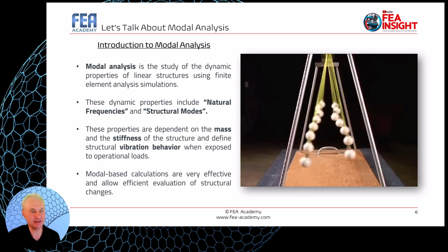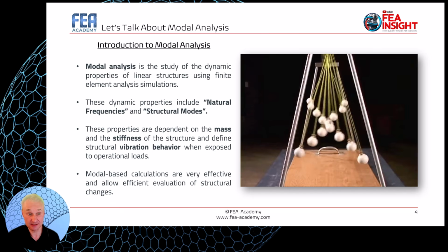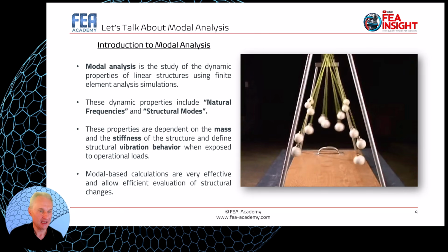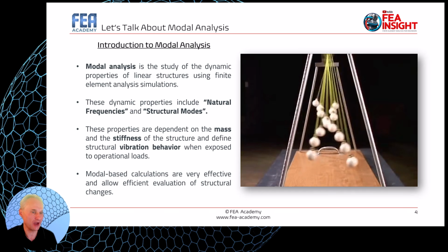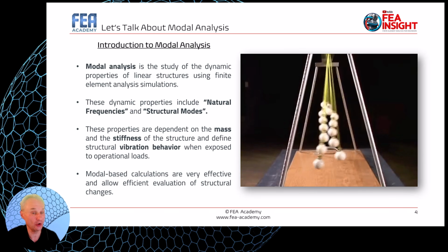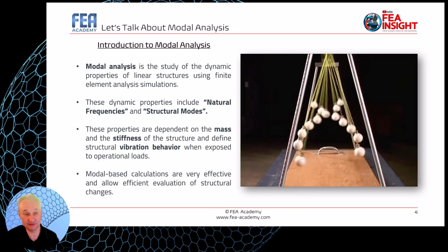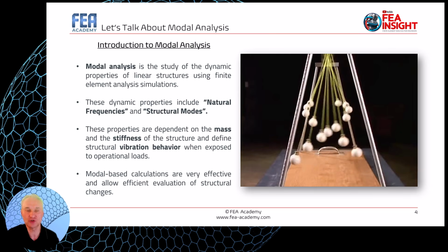These properties are dependent on the mass and the stiffness of the structure that you want to analyze by modal analysis, and define structural vibration behavior when exposed to operational loads. Model-based calculations are very effective and allow efficient evaluation of structural changes.